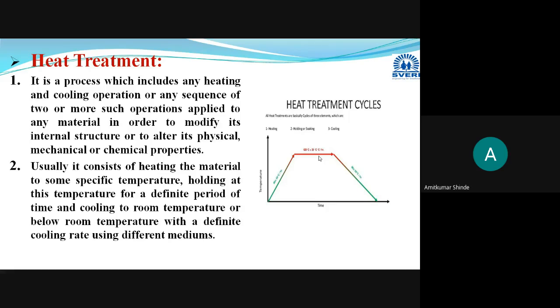and the type of steel, whether it is plain carbon steel or alloy steel. If it is alloy steel, then soaking time increases. If a smaller size component is there, then soaking time decreases. If a larger size component is there, then soaking time will be more. In this way this process is conducted.